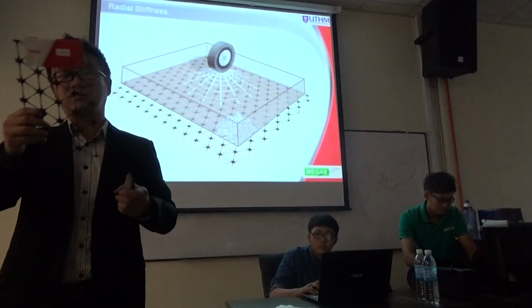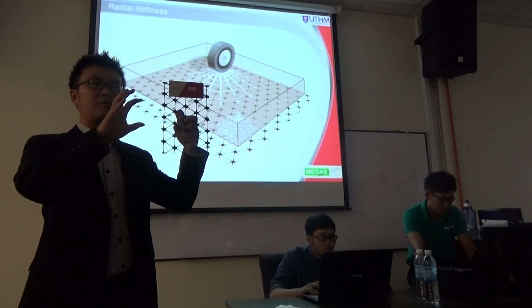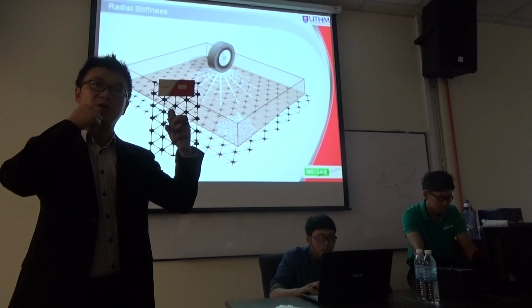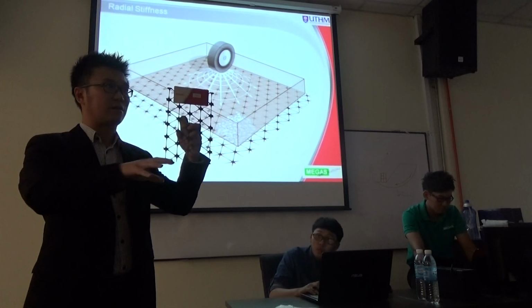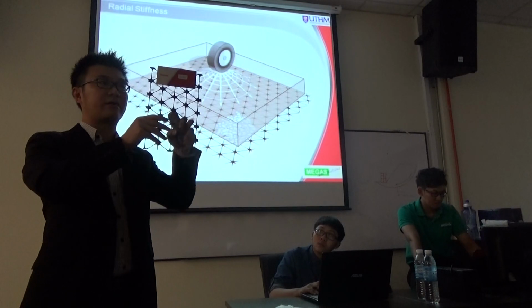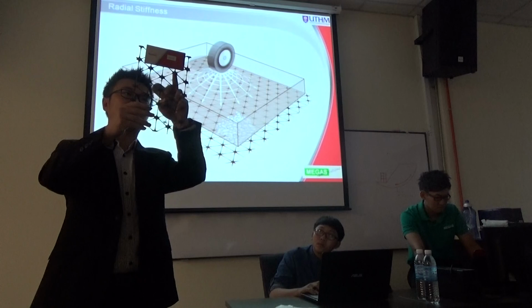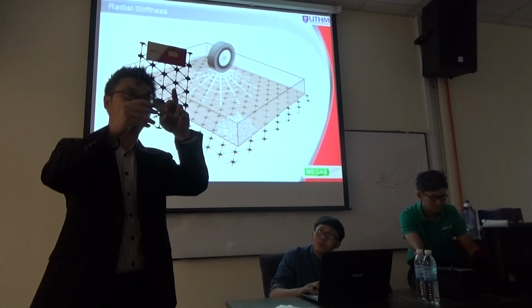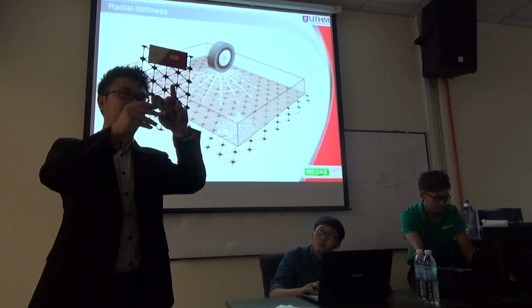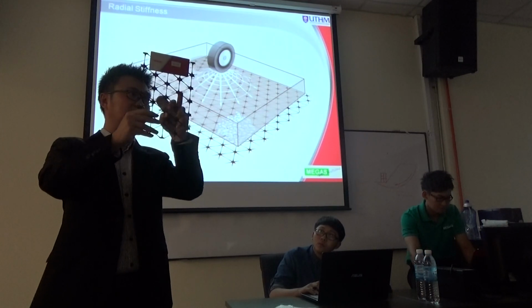So the research and invention of this triaxial geogrid is to take care of that, so that the load distribution is more complete and more efficient onto the ground. When we talk about more efficient, we are talking about multi-directional. The load distribution of this triaxial geogrid is not a triangle but a hexagon, which is almost like a circle.